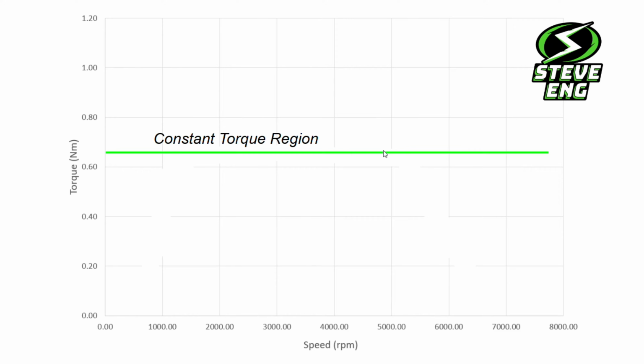You might remember in part 2 I did show that as the RPM gets higher, torque does tend to start reducing due to eddy current losses, and you can calculate that, but you need some really detailed motor parameters which aren't really readily available. But if you work within the manufacturer's operating range of the motor in terms of the number of cells you're running on, then I don't think the losses should be that significant. I did find that I was running into that problem because I was operating outside the manufacturer stated range, like I was going above 8 cells, whereas that was stated to be the maximum for that motor. So I think we're all right with our straight line for now anyway.